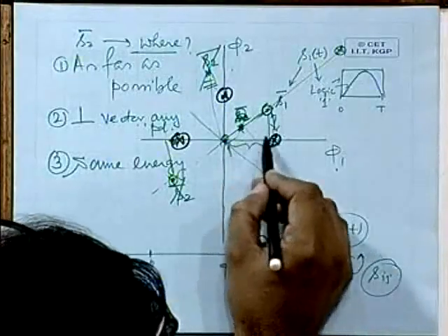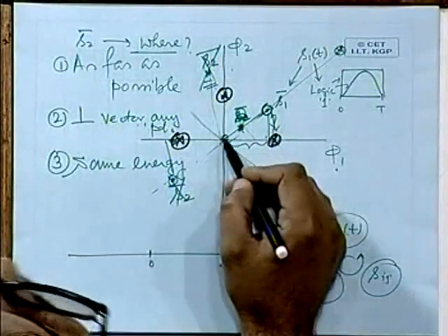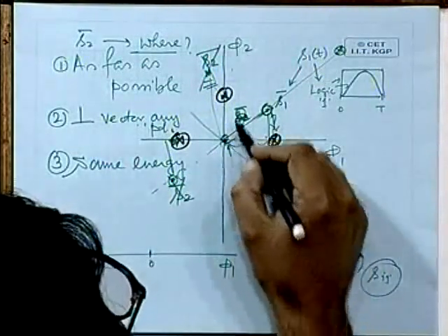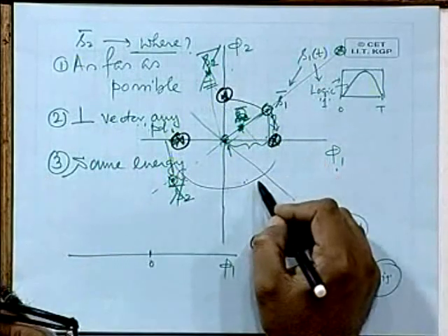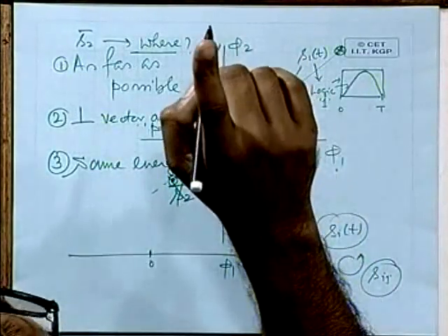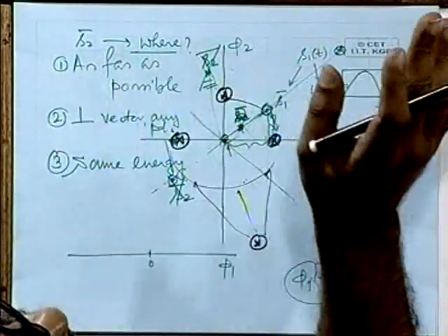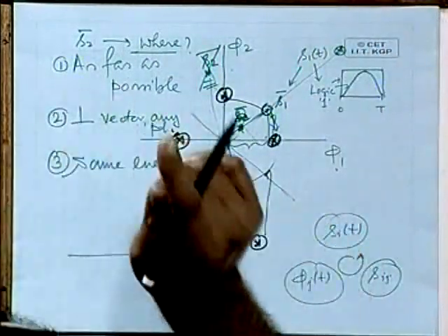The fourth point, first of all, should be equidistant, because these points are equidistant from the origin. All of these symbols have the same energy. So, why not the fourth one? When all the symbols are equally likely, this also should have equal energy. So, maybe somewhere here. If I draw a circle, it should be on a circle somewhere, at least that much to reduce the average transmission power. So, this point could be here, could be here, could be here, but you also said that not necessarily that, let it be here, because that also takes care of something else. Maximum separation, and this separation is fundamentally necessary for the purpose of good detection, isn't it? Good decision ultimately, isn't it? So then my point is proved.